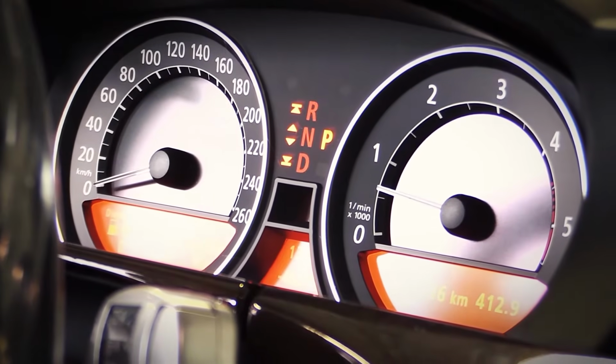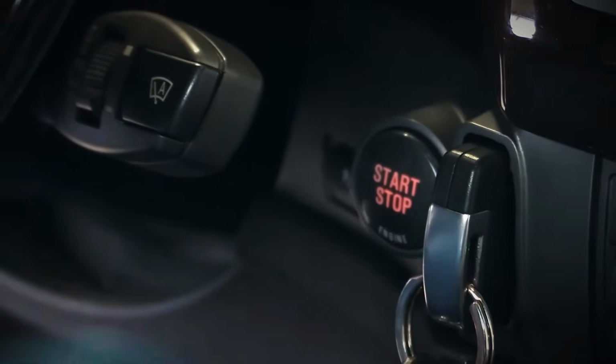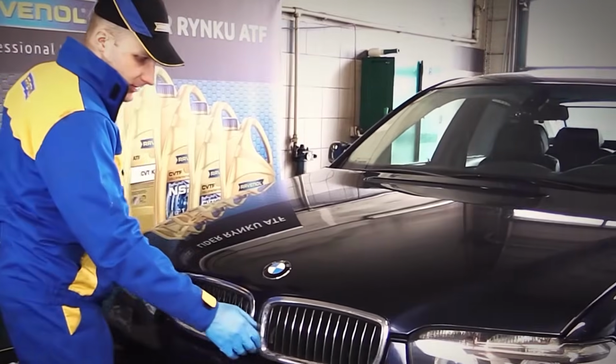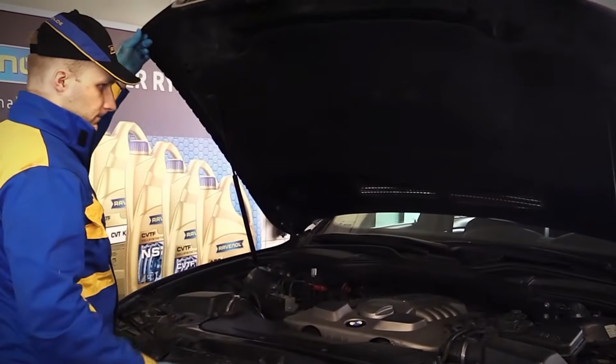If the air bubbles move in the opposite direction, you must switch the vehicle's engine off and replace the inlet and the return on the 2 clutches. If the appliance is correctly connected, the maintenance works can be carried out. First of all, the transmission is flushed.